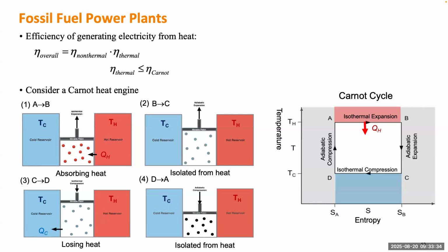In the first step, the heat comes from the hot reservoir to the tank. In the third step, the heat leaves the tank to the cold reservoir. The sizes of the two heats are different, and the gap is how much work this engine can do. When the engine is doing work, the pressure of the air decreases and the volume increases.